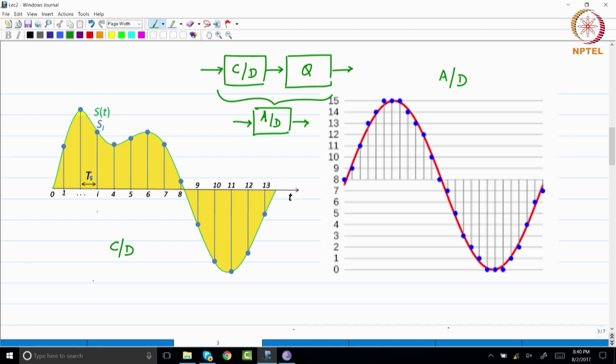So, this is the point that we wanted to mention. Keep in mind that here we have continuous amplitude in the discrete time domain, so we do not have any loss of information due to quantization. Here it is discrete amplitudes. The minute you have discrete amplitudes, you have lost some information. So that is a very important element.